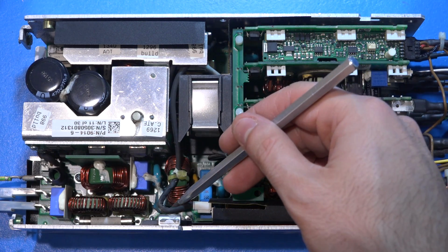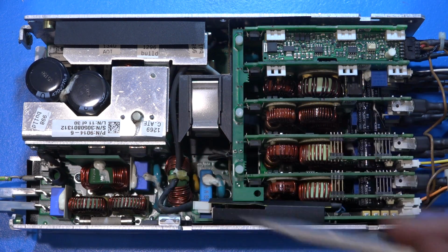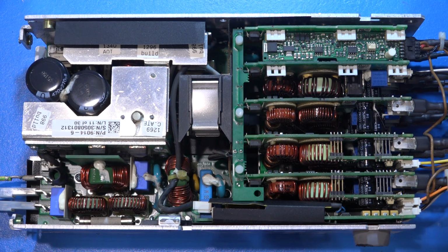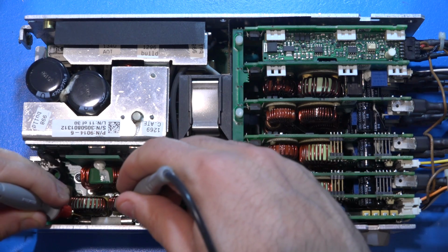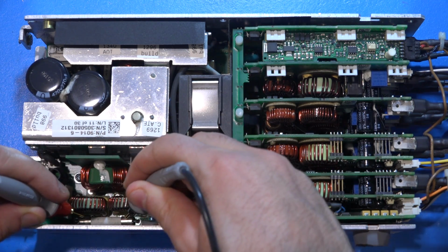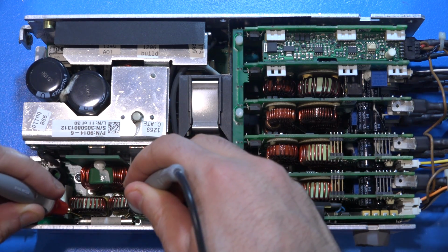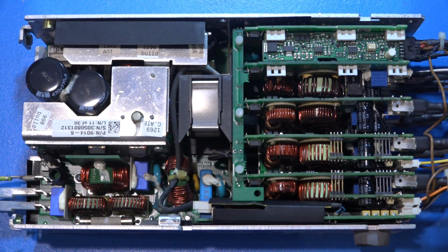And the rectifier is right down there. And there's a fuse right down here. And interestingly enough, that fuse, you can see I'm in continuity, and that fuse is dead. Now, of course, you don't want to just go ahead and replace the fuse because we have to find out why the fuse has died. And the fuse has protected, luckily, whatever the problem is.